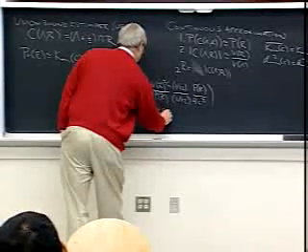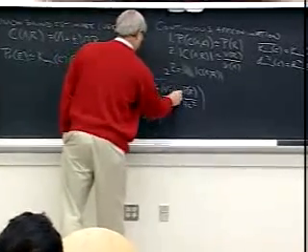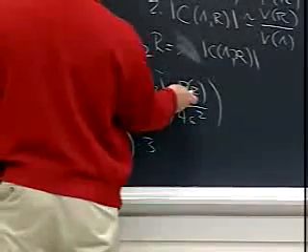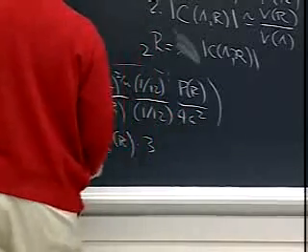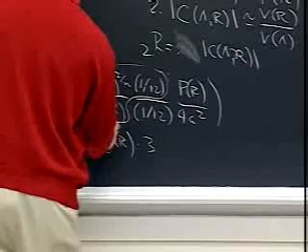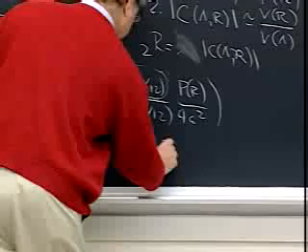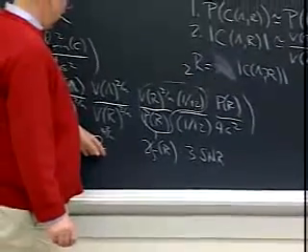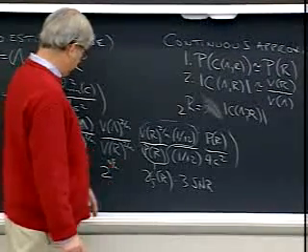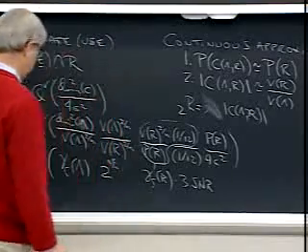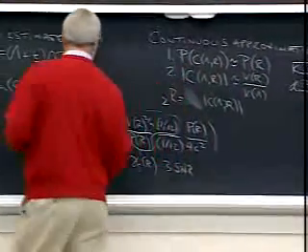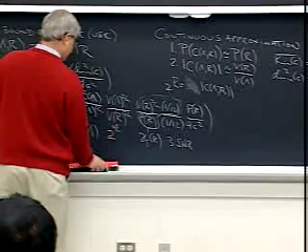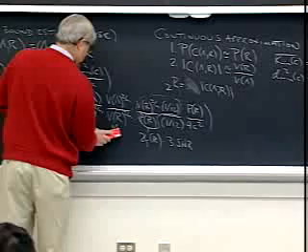This is the shaping gain of the region, these three things together, times 3 times what's P of R over sigma squared? That's the SNR. That's the average power per dimension, and this is the average noise power per dimension. So I've used up these in that. So I've got a 1 over 1/12. That's 12 times that. So this is 3 times SNR. And let's see. 2R over N is just 2 to the... Is that just 2R? Because the rate is normalized by the dimension. Yeah. And furthermore, it's minus, because it's upside down, so it's 2 to the minus 2R.